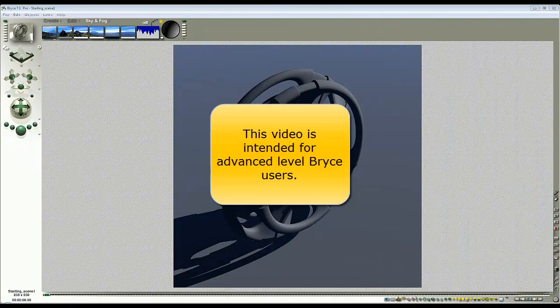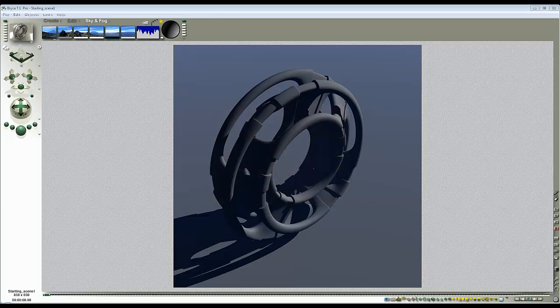What I want to look at doing here is to upgrade true ambience gel lighting to incorporate hypertextures to get more light output out of the gel. Previously this was achieved by stacking the gels on top of one another, but this was render inefficient because transparency layers used extra ray paths up. So I've just got this scene as a simple object that I made in Wings 3D and an infinite plane.